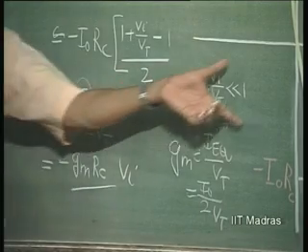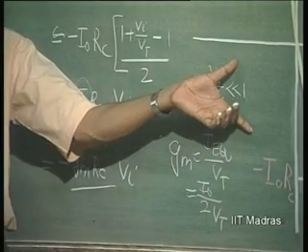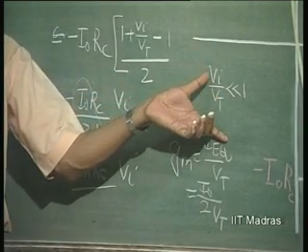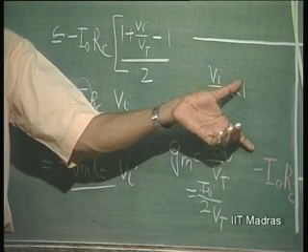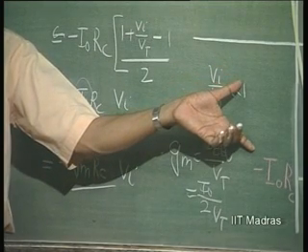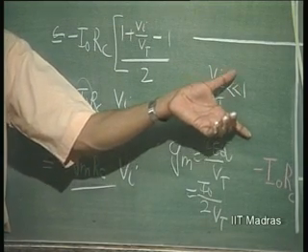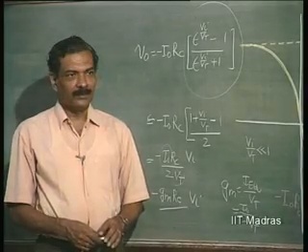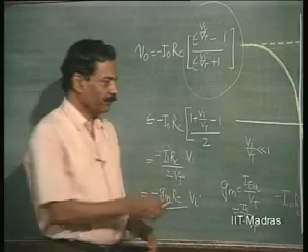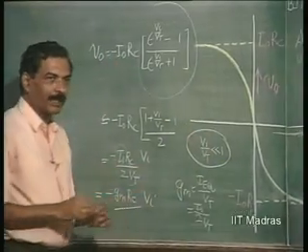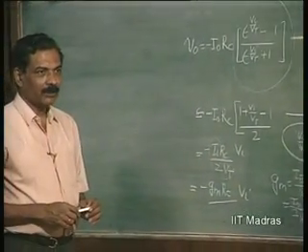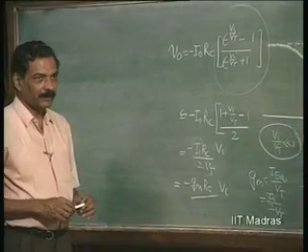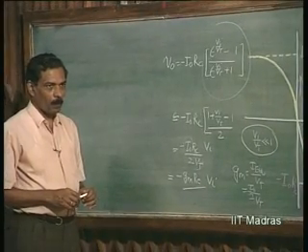That means small signal here means Vi is again much less than Vt, the same thing that we had used earlier for the common emitter amplifier. So, now this defines what is meant by small signal in the case of the differential amplifier.